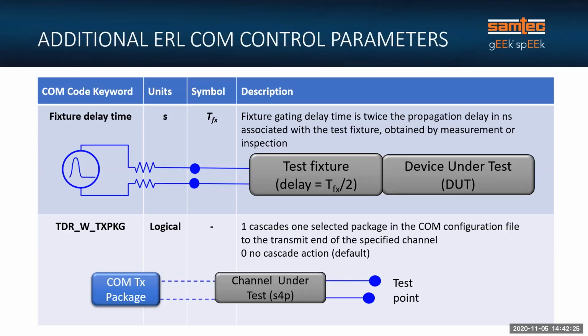Moving forward. Hey, Rich. Another question. Why not de-embed the fixture in the model instead of gating it? Good question. You can do that, but the industry, in terms of the standards communities, has very low confidence in de-embedding between various different companies and instrument manufacturers. And there are a lot of ways that you can get into trouble doing that.